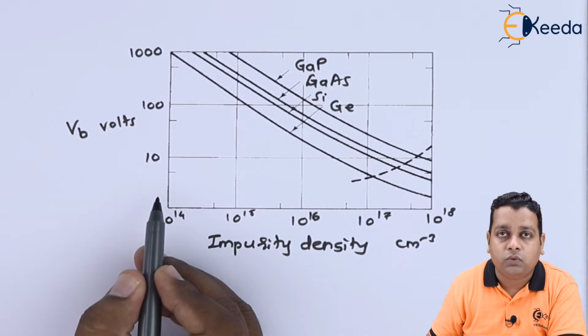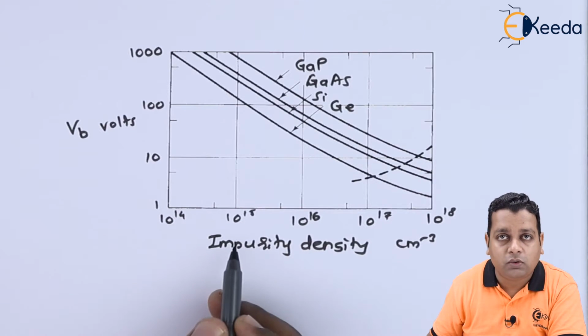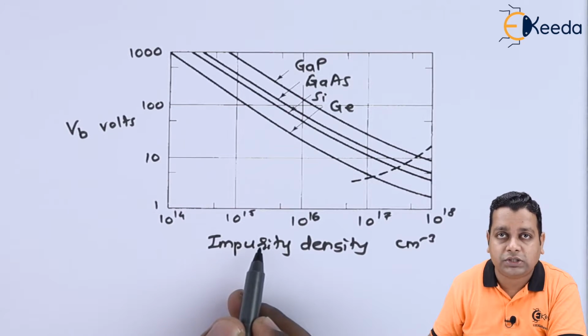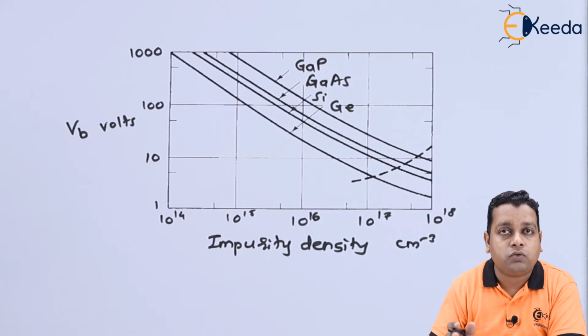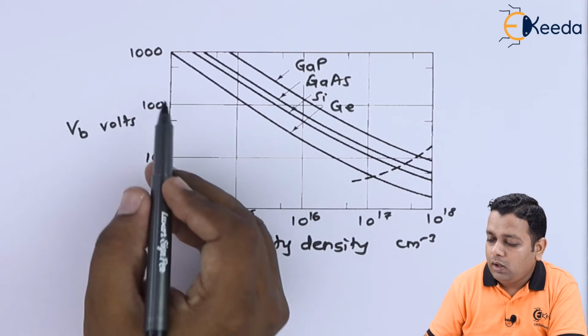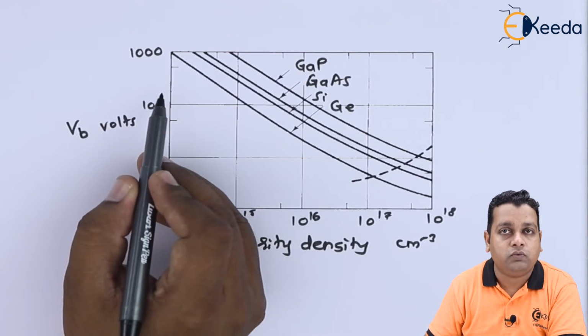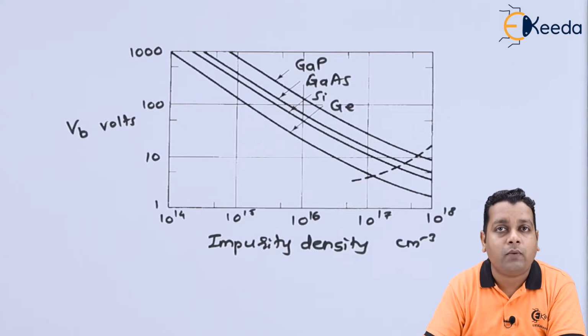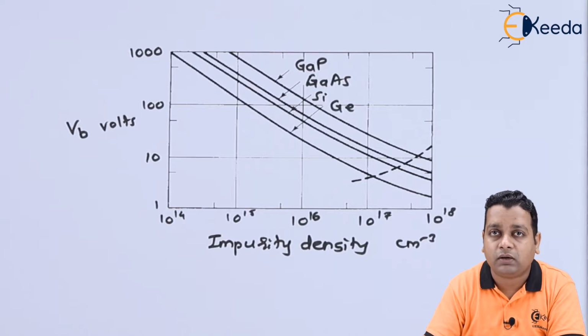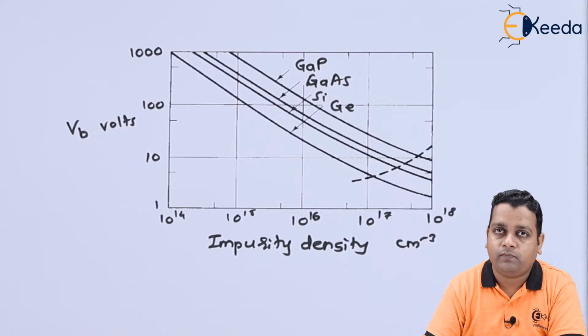And if we don't have much of the doping concentration or the impurity concentration, that time we have to go for a higher order of the breakdown voltage, and after that the avalanche multiplication, the avalanche effect, will be in operation in the device here. Now we discuss the very important topic for this particular device, that is how exactly the negative resistance is obtained.